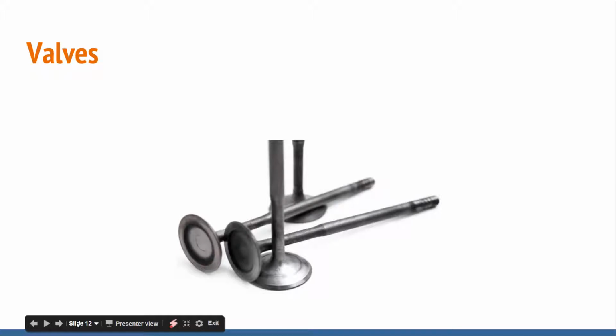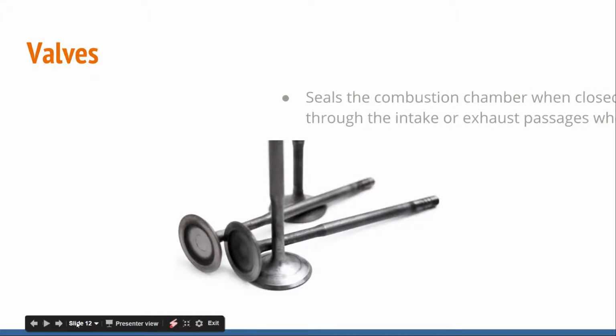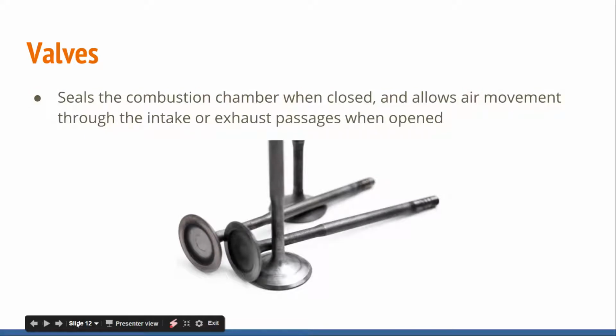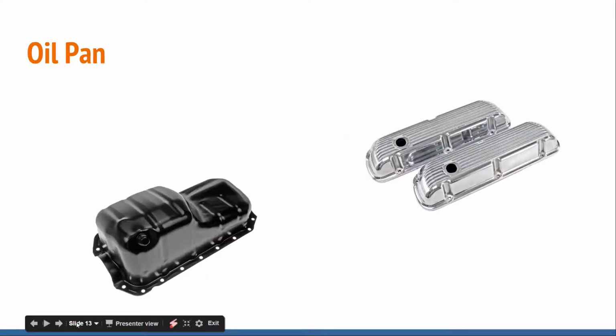So we'll talk about the valves here. The valves seal the combustion chamber when closed, and when open, allow air movement through the intake or exhaust passage. So very important for such a small part. They just act as a one-way valve. They last a long time.